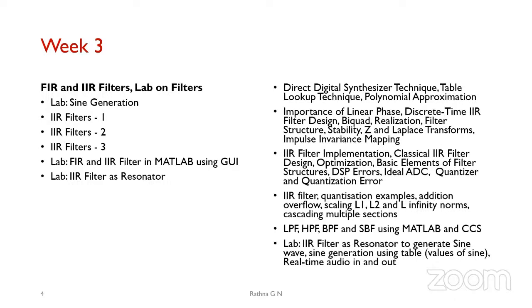Whereas using a math function, you know that I had to use the libraries, which have to be completely loaded. It is not only for one function that it has. And even using tables, if it is long data, your memory is going to be occupied, or you may overflow in that case also. For real time, it is better to have an IIR filter designed for generating sine waves, so that I can get it continuously.